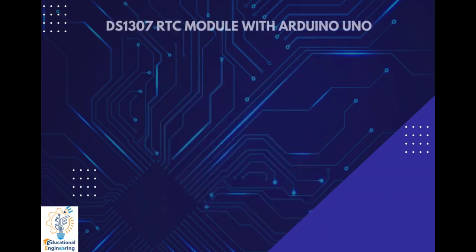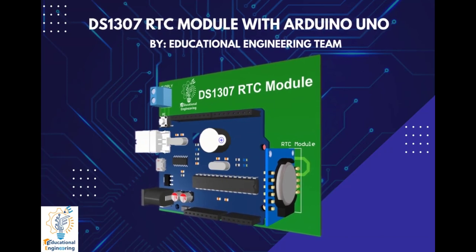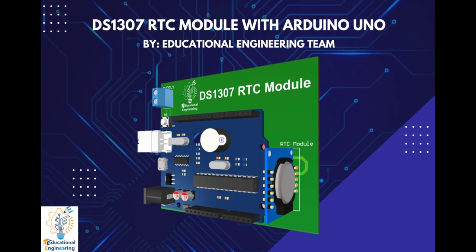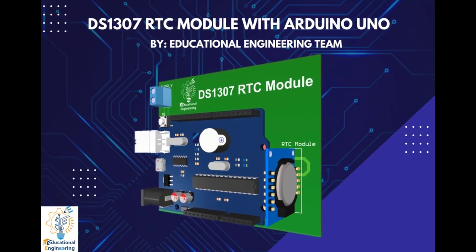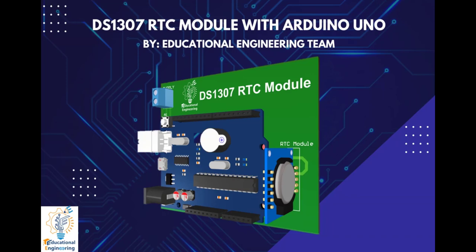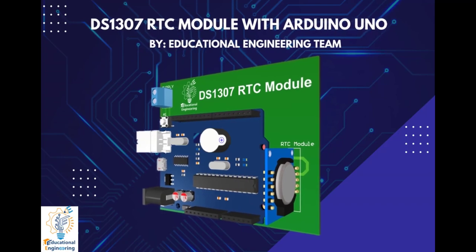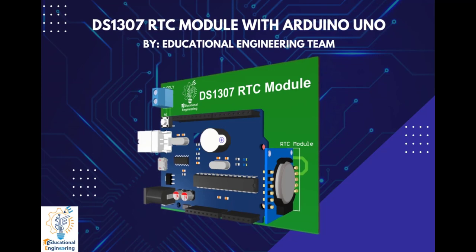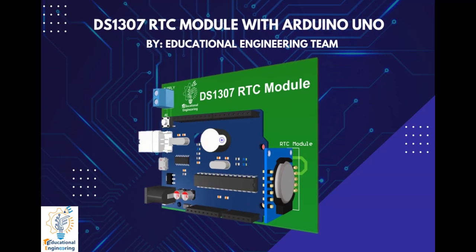Interfacing a DS1307 real-time clock or RTC module with an Arduino Uno is a technical procedure that enables the use of a compact, reliable RTC module with an Arduino board. The DS1307 is a real-time clock module that uses I2C communication to interface with microcontrollers. The module is designed to provide accurate timekeeping for devices such as microcontrollers or single-board computers. For the connection, SCL pin is connected to A5 and SDA pin is connected to A4.